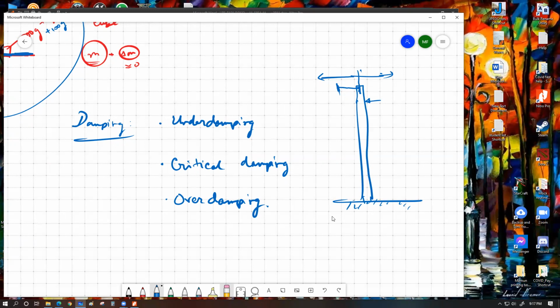It means it is going to lose all of its energy while completing this quarter of its full oscillation motion, or basically it will immediately come back to the initial position. It will take time, but it will not get past the equilibrium position. If the object is pushed to one side, it will be pushed because that's the effect of an external force. But whenever it is allowed to continue, oscillation will simply not happen. It will slowly move to the equilibrium position and remain stuck there. This type of damping is what we call critical damping, where even a single oscillation does not take place.